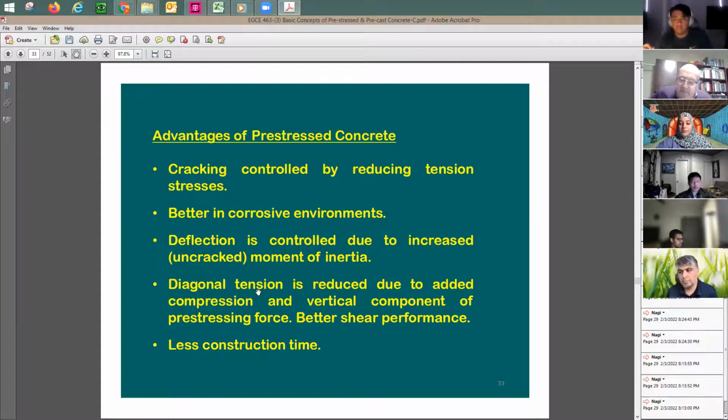What does this do? I mean, what's causing it physically? I'm going to say the interlocking between the aggregate, right? So, for example, if I give you here a section, it's going to be 100% exposed to tension, concrete section. It has some rebars. Now, think about any shear friction resistance. Would you have any if the section is going to be under tension? It's going to be nothing, right? Because when you apply tension, you open the interlocking between the aggregate particles and the cement.